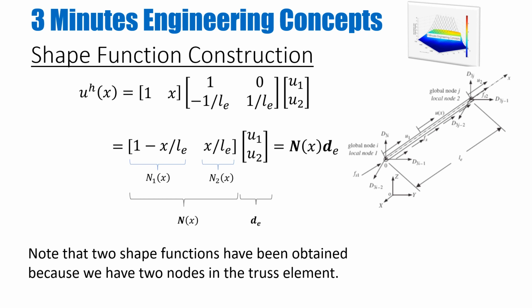In the present case, we were using a 1D truss element, so we had two nodes, and hence we had two interpolation functions. In this course, we are only considering linear shape functions, so based on that, we derive the relationships. However, there could be higher order polynomials which can be used as shape functions, and again, you can look into other books and literature which discuss that.